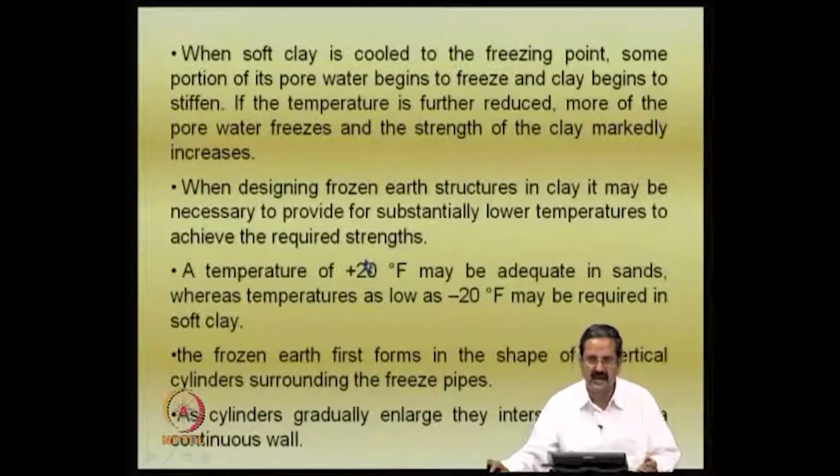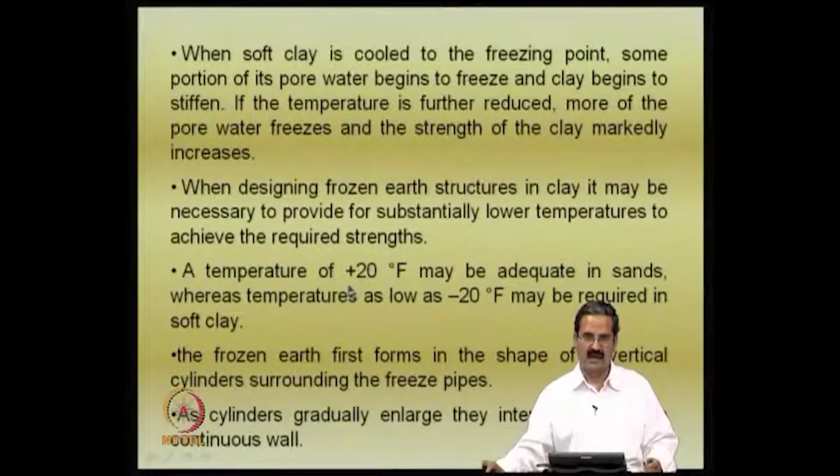The thing is that we know the lower the temperature, the more the stiffening, and one should be really careful, because the temperature gradients should be properly understood. You should have an adequate margin of safety to see that you get the required strengths. A temperature of plus 20 Fahrenheit may be adequate in sands, whereas temperatures as low as minus 20 Fahrenheit may be required in soft clays.